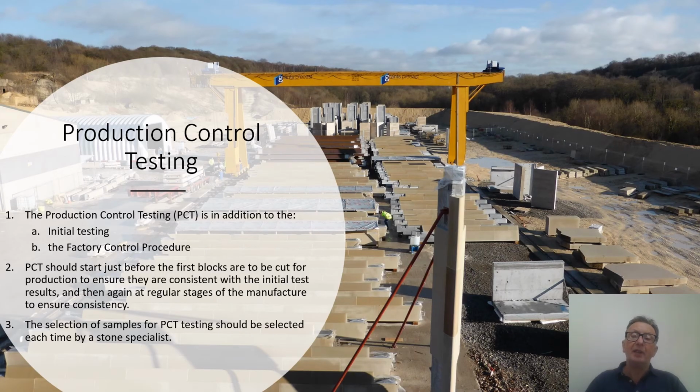Production control testing is designed to give improved confidence about the quality of the stone that's going to be supplied throughout the duration of the project. As such, the production control testing samples should be started just before the key first blocks to be cut for the production for the project to ensure that all material from start through to end is consistent with the initial test data that you have.